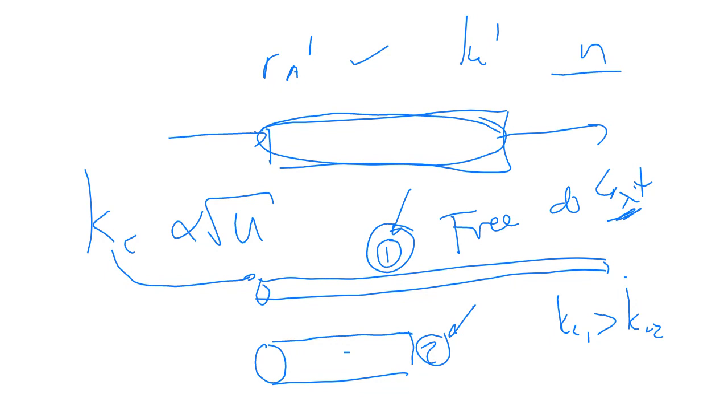The pressure drop. The pressure drop? Yes, okay. So heat transfer is definitely affected, but long and thin will be good for heat transfer because my heat transfer area per volume is equal to 4 over the diameter. So the thin one will be better in terms of heat transfer.